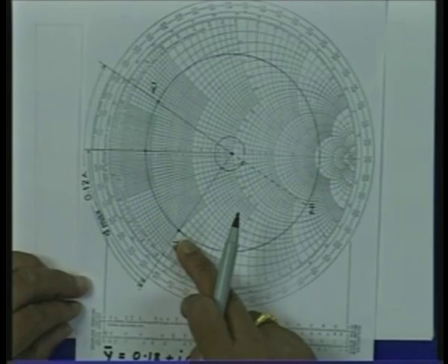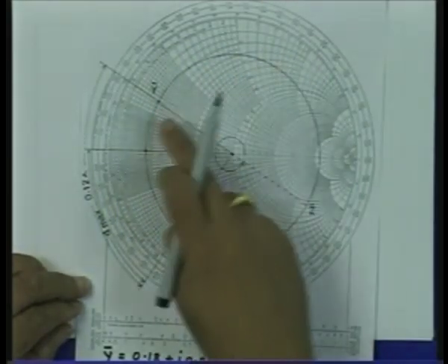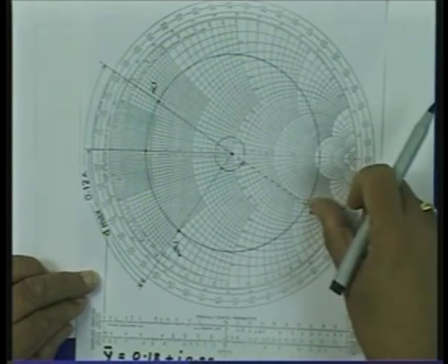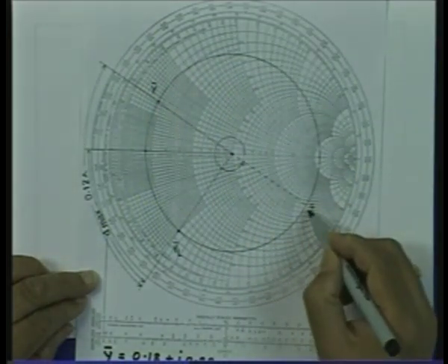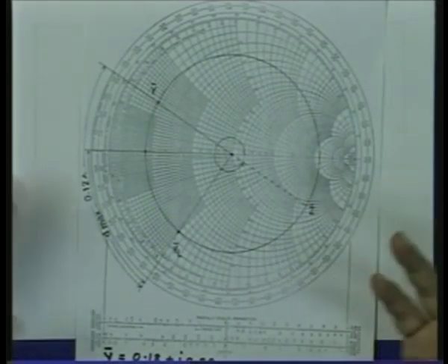So see, the interesting thing: we started on the Smith chart as the admittance Smith chart, marked this point which was the load admittance, drew a constant VSWR circle, and moved on this to find the admittance at a distance of 0.12 lambda. Just by taking a diagonally opposite point, I get the normalized impedance, and beyond this point I can start treating the Smith chart like an impedance Smith chart.